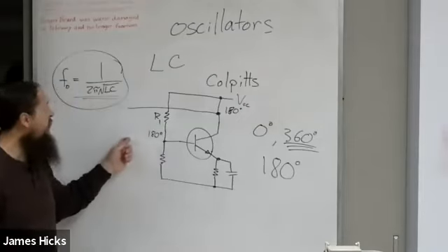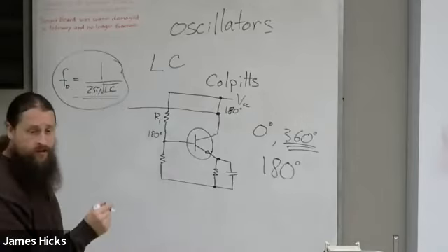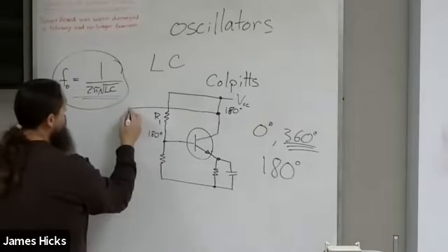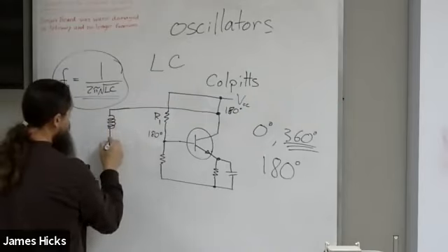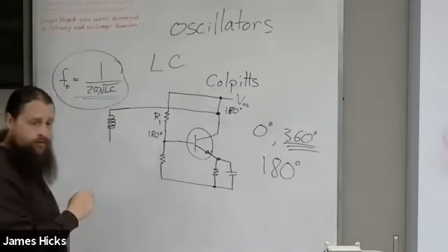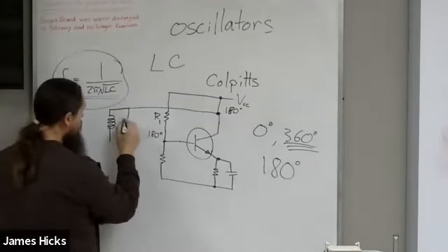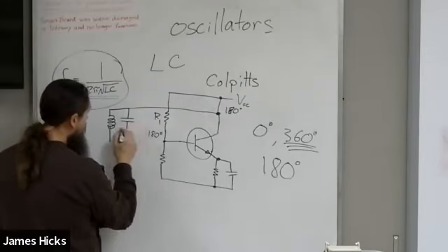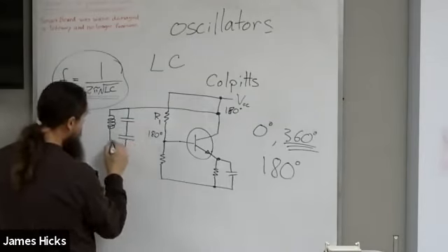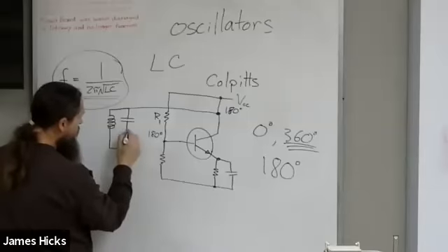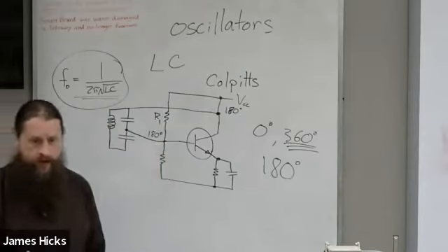What's the easiest variation you could do on that Hartley oscillator? Well, don't center tap the inductor. Center tap the capacitor, like that.